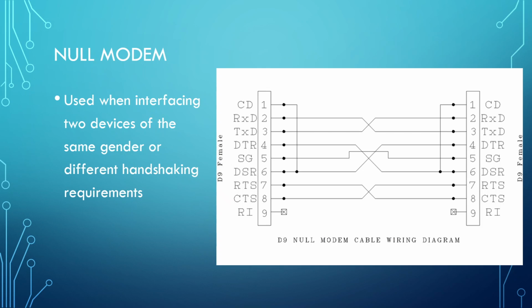All right. Null modems. Basically the whole point of a null modem, as you can see here, is that our RX and TX data get flip-flopped. Some other things get flip-flopped too, our RTS and our CTS. But notice our CD gets pulled down to our DSR and things like that. The whole point is basically to trick each other.